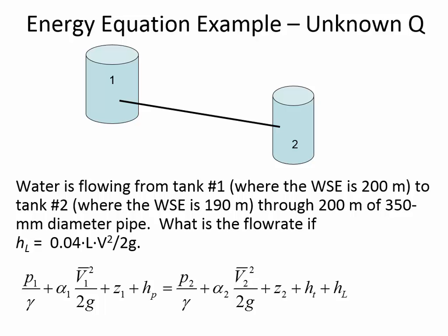Okay. So yeah, he's remembering that in the energy equation, we've got a lot of terms here. If I just pick some random spot in the tank, I don't know what the pressure is right there, so I'm going to have to calculate the pressure. Where's an easier place for me to pick as location 1? Yeah, up here. Because I know a lot of things at the top of that tank. I know the elevation, I know the pressure, I know the velocity of the water. Since it's a big tank, the velocity is 0. So I know a lot of stuff at 1.